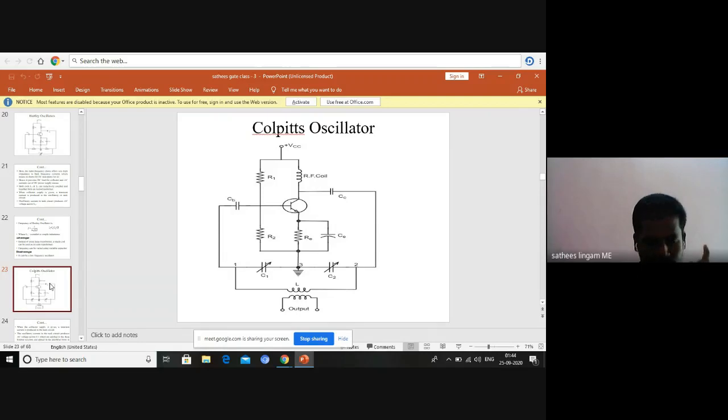So VCC is on top. From the VCC we are receiving the supply, that means voltage is getting stored in C1 and C2. Then from C1 and C2, the inductor L is getting energized. So there is charging and discharging; after the inductor is completely depleted, it is getting charged back by C1 and C2. So at last that loop continues. Then positive and negative pulses are created, which is called oscillation.